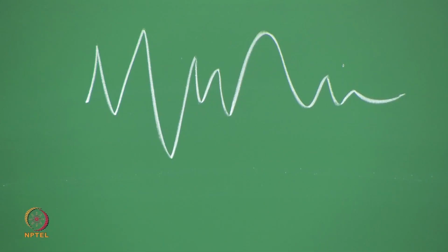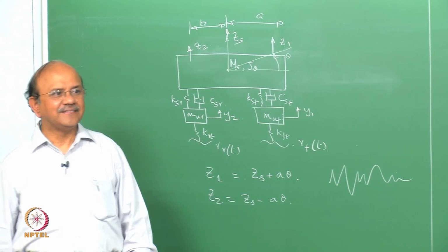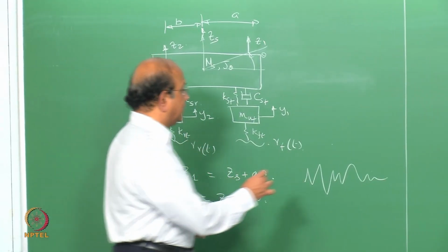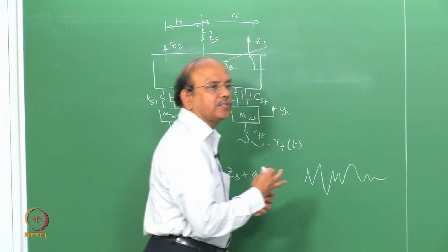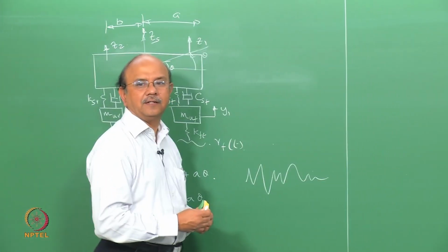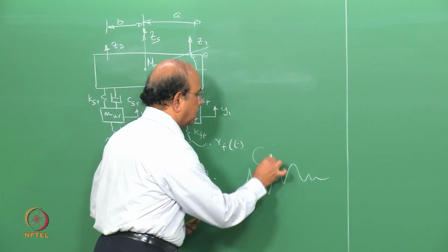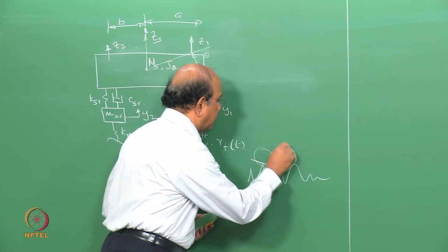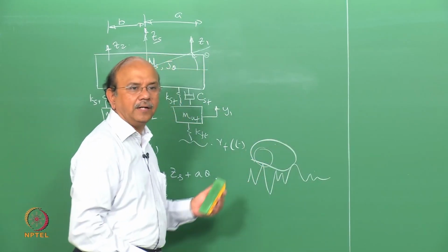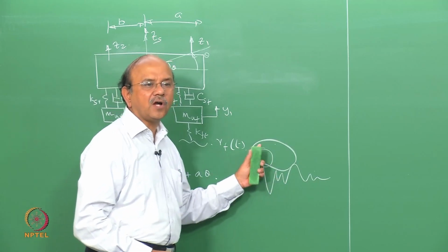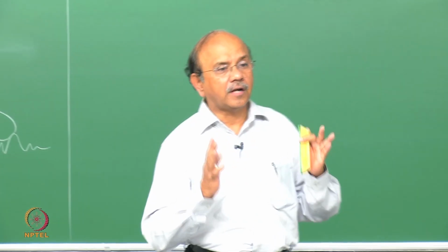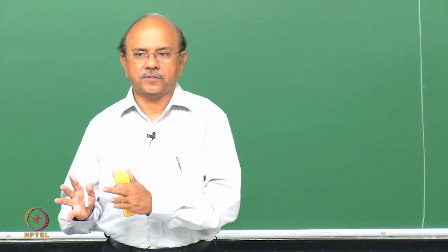Speed also matters. Yeah, okay, that's very good. We're going to consider the speed. Tire may damp some of the... Correct. Tire acts as a filter. That is what is called the envelopment characteristics of the tire. So the tire, as it goes, is not going to follow the profile exactly, and it is not the true representation of the road. What the car sees is not the true representation of the road.